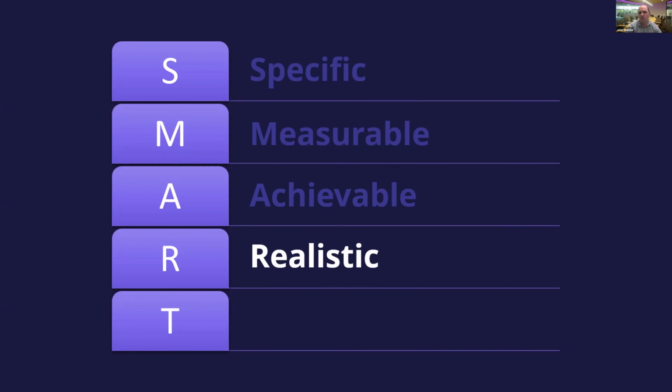Set realistic goals for things like scrap rate and OEE, which is overall equipment effectiveness. No machine will produce 100% good product and be available 100% of the time. Set realistic goals for things like changeover. Remember, it's costly to expect something like a 5-minute changeover if the machine changeover is infrequent, or if the machine is idle between batch changes because of other production reasons.